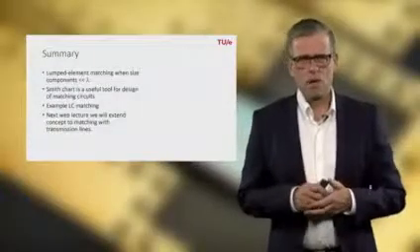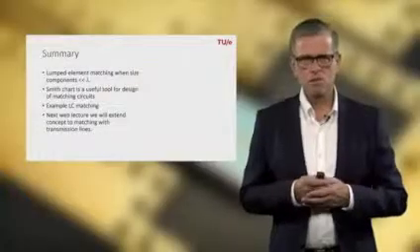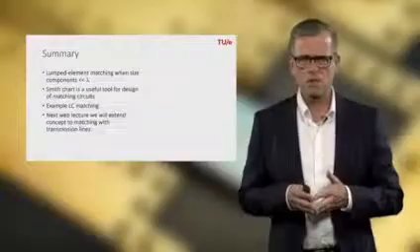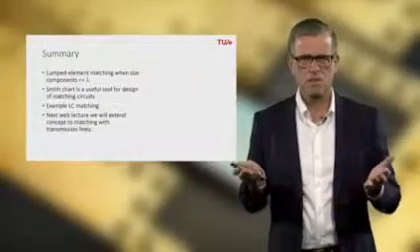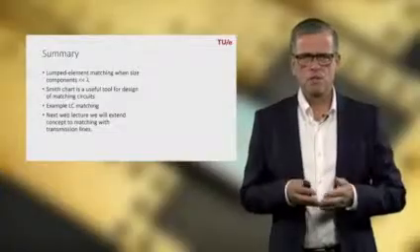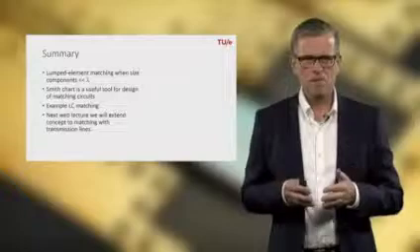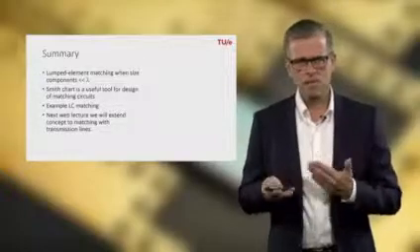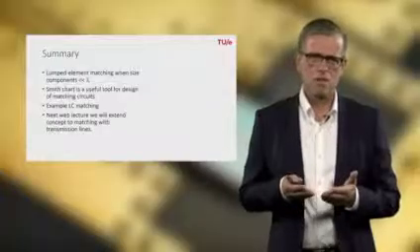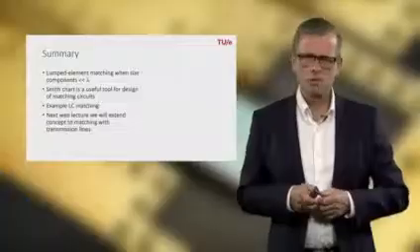To summarize this web lecture, we've shown that lumped element matching can be used, but it's important that the size of the physical components should be much smaller than the wavelength, else it simply does not work anymore. The Smith chart appears to be a very useful tool for the design of matching circuits. We've shown an example of LC matching, and in the next web lecture, we're going to extend the concept of matching with lumped elements to matching with transmission lines. Hope to see you back next time.